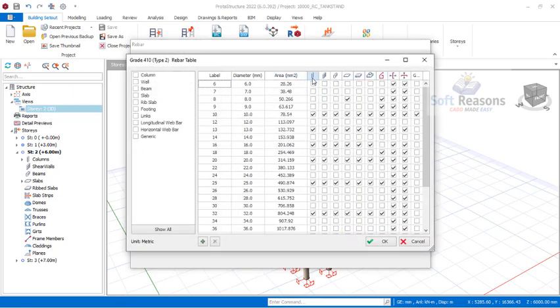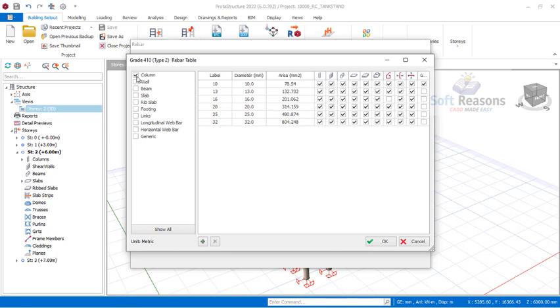So we will be considering columns. We have columns in the structures. For the columns right there, or you can also check them from here. Once you check it from here, you can see we don't need 10 for the column. We don't need 13, we need 16, we need 20, we need 25. We remove our 32 right there. For the column, that is it. Activate the beams.